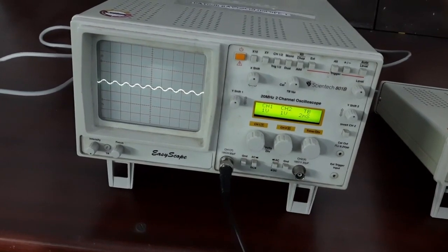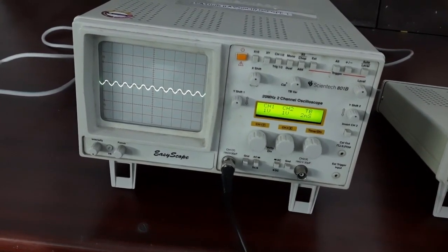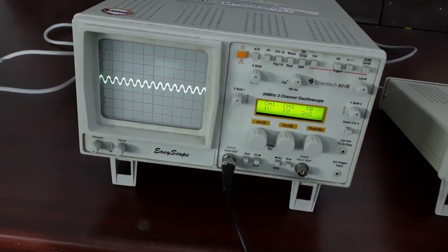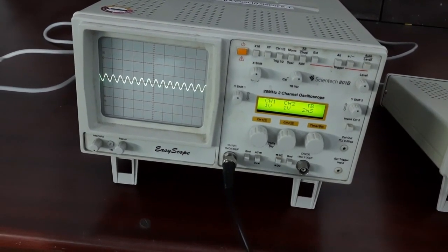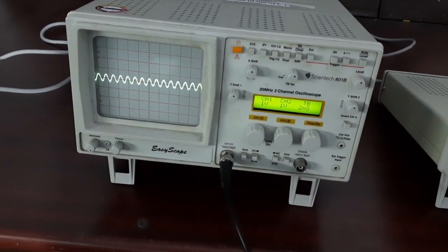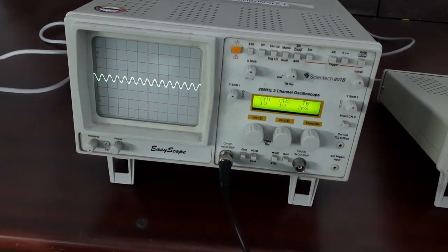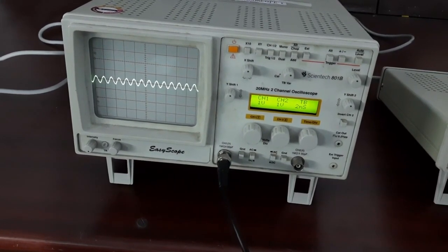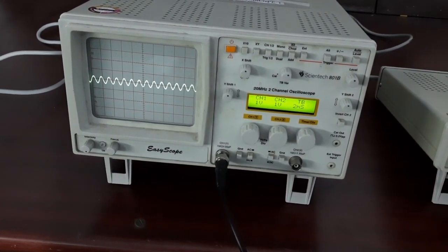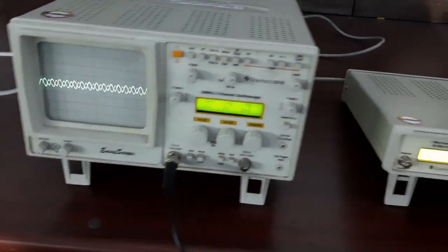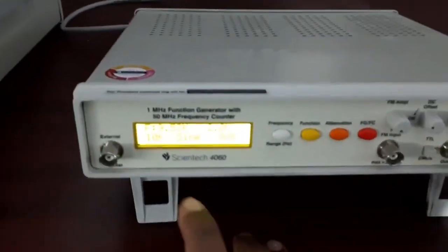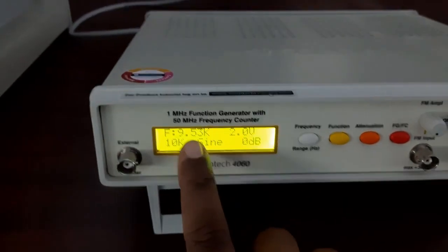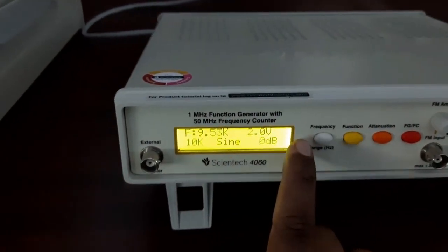We can see there is some output coming, because we are increasing the frequency, and the high pass filter will allow high frequency. Now you can see a total sinusoidal waveform is coming, because we have increased the frequency enough. It already crossed the cutoff frequency of the high pass filter. As you can see, after the cutoff frequency, the output of the high pass filter will be shown on the CRO. Now the current frequency we are giving from the function generator is 9.53 kilohertz.